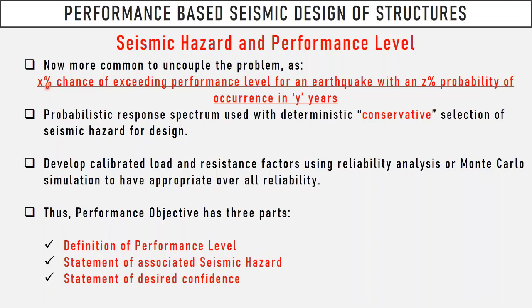What I mean is that if you increase the sampling numbers in your uncertainty, in our case, the uncertainty is the ground motion. If you increase the ground motion parameters or the number of ground motion distributions that you use, of course, your reliability will get higher, and your results will be more confident at the end. But of course, it is a huge computational approach.